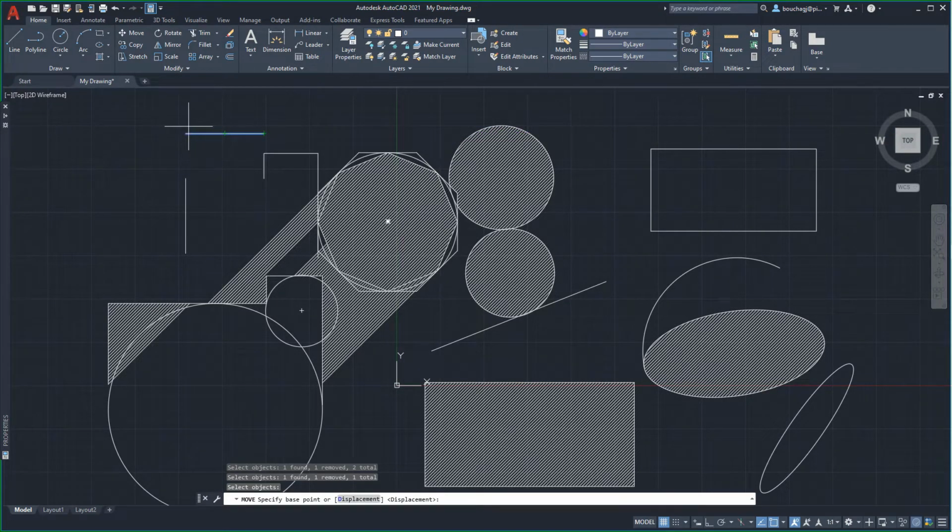By hovering our cursor over the selected line near the end of the line, the endpoint snap is recognized by the software. As mentioned in the previous videos, develop a comfort level in trusting the software to connect with the snap point being detected and resist the need to touch the detected snap point. Left-click to select the chosen base point.